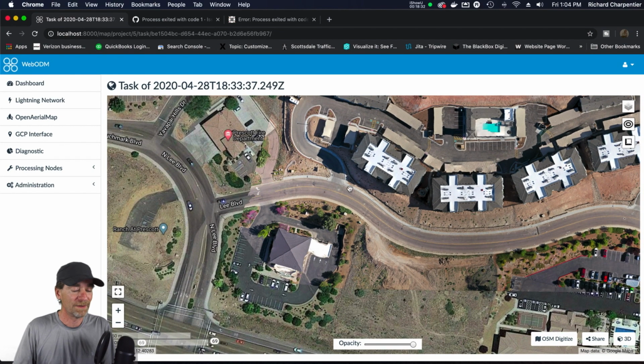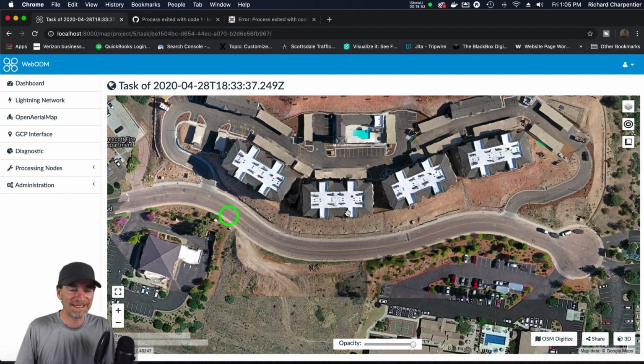But we don't need them perfect unless we're dealing with measurement and dealing with survey grade accuracy. If we're just doing this to present a two-dimensional orthomosaic of before and afters, let's say for my construction progression reporting work, this could get you there. So, and this is decent enough.